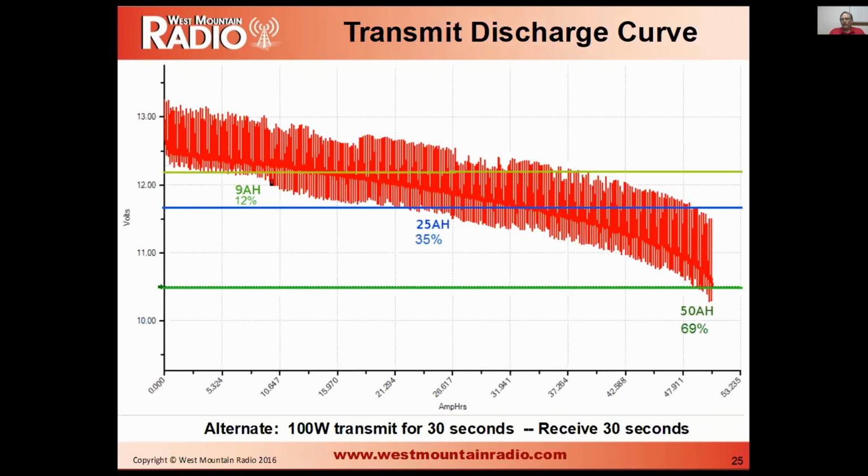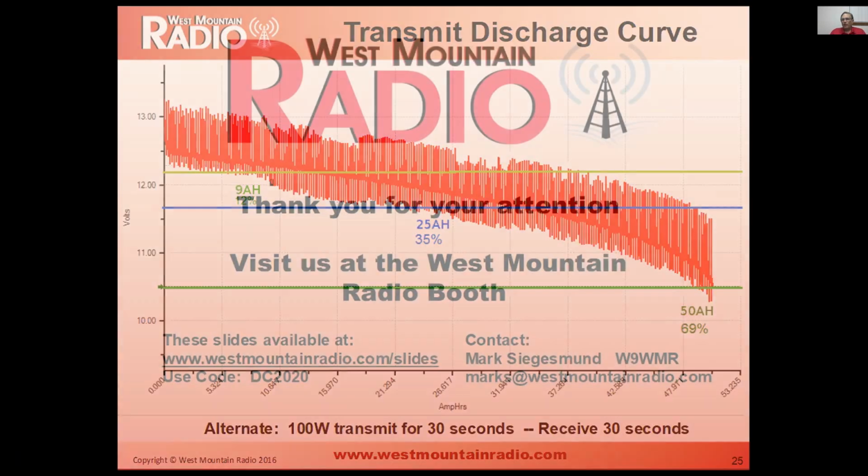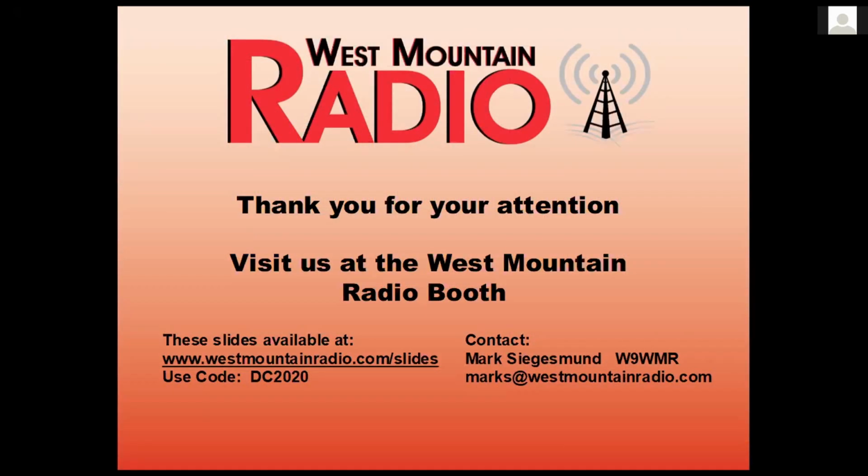So if you want to fully utilize the battery, what you need to do is boost the voltage up to something that you can utilize. And then you can run that battery all the way down to the 10.5 volts that the manufacturer allows you to run it down to, and get the full 100% energy out of that battery. So how does that work? It almost feels like you're getting something for nothing. So how does that actually work?